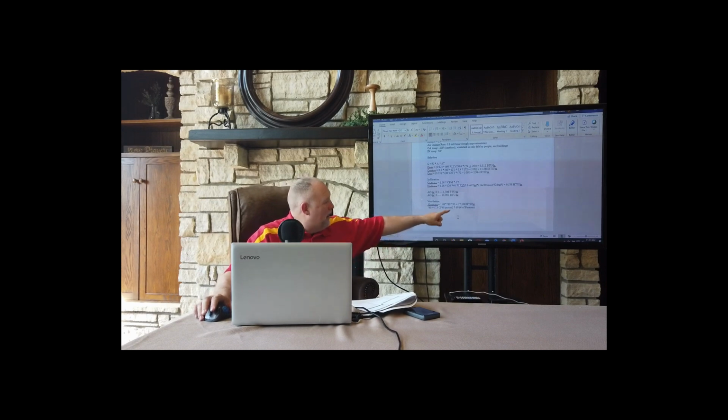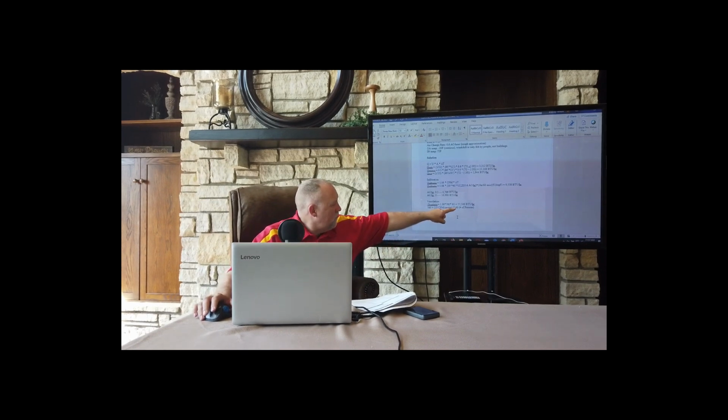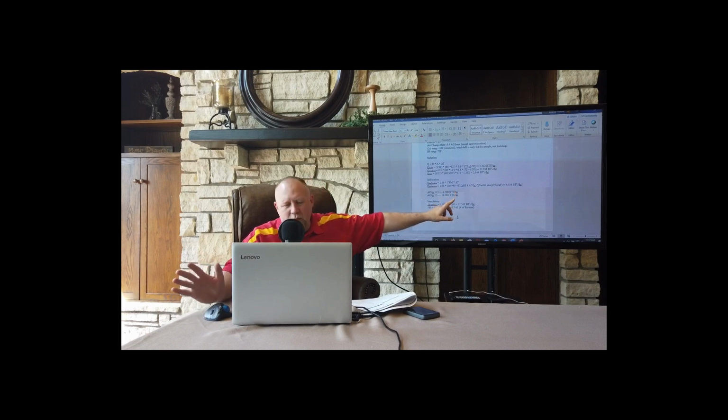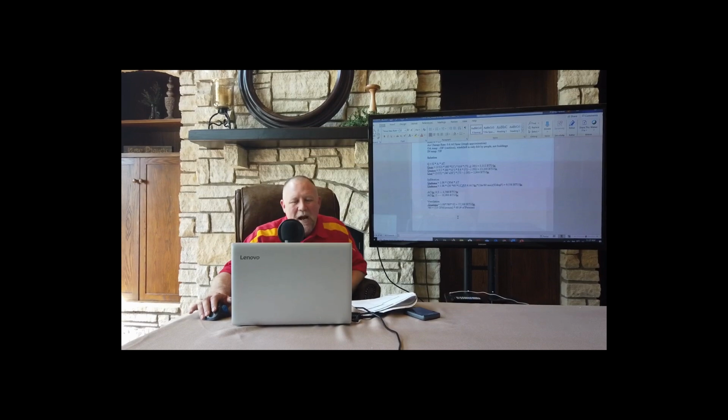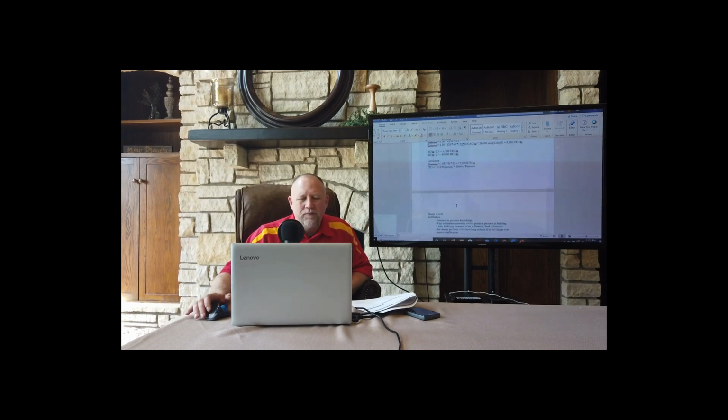Now check this out. If this is a classroom set up the way it was before COVID, and we had 60 people in there at 13 CFM per person, that's 780 CFM of outside air just for ventilation for the occupants. Check out how much energy that we are consuming there. It dwarfs everything else, including ventilation.